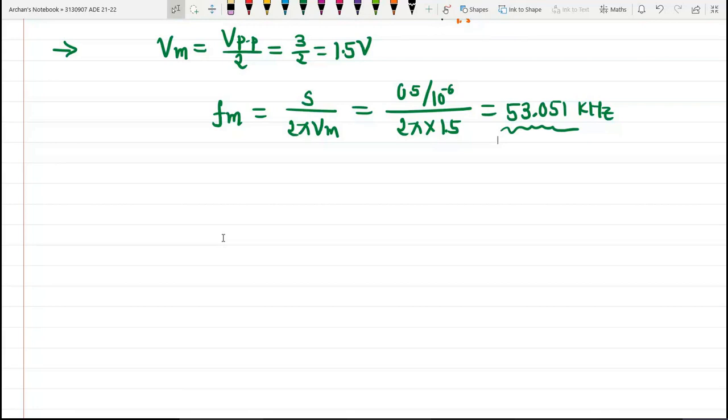Okay, so this doping will not be exact, and this is the reason why we will not get the exactly matched characteristics in this case. Okay, and what we are doing in operational amplifier, we are using the differential amplifier as our input, where we are using the emitter bias circuits, two emitter bias circuits, which means we are available with two semiconductor devices involved in it. Okay, so these two transistors of the input stage are not perfectly matched.